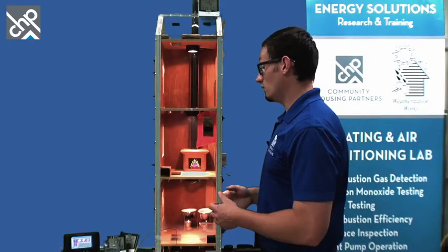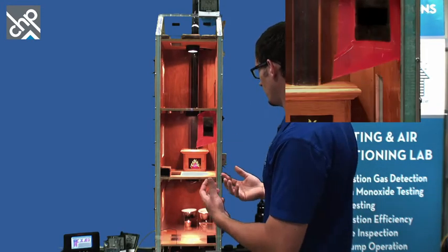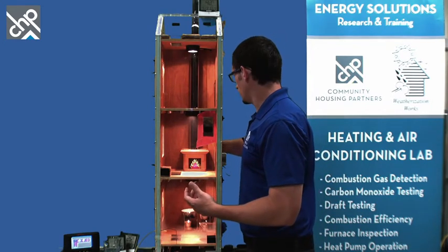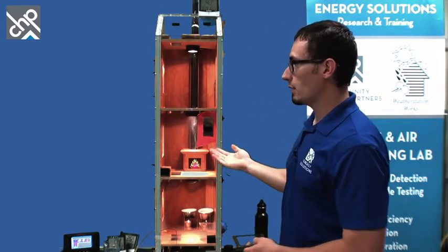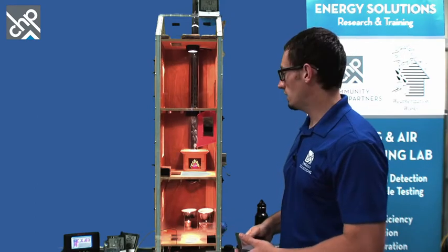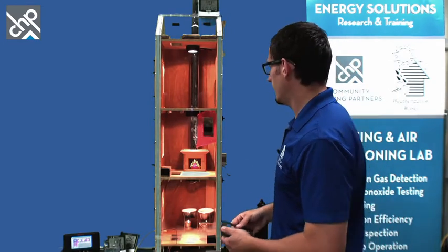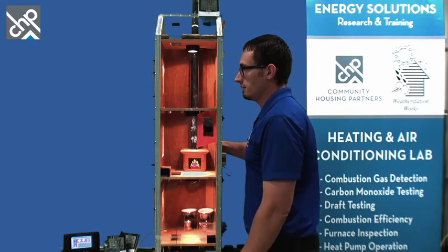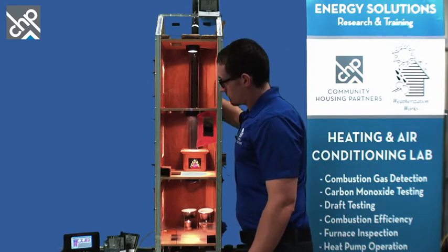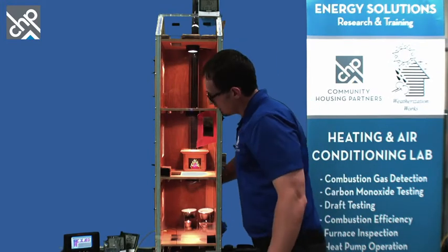So less than ideal. So my exploration of this ventilation conundrum is, well, we've only got two options here, right? So we either provide dedicated makeup air to the appliance, and that maybe could be done through, if that's a furnace, it's a 90+ furnace, air originating from outside, or we make the house leaky again. So if I seal this up, make the house leaky again.